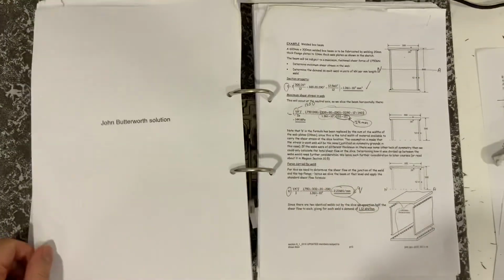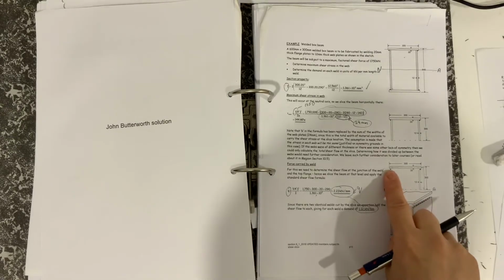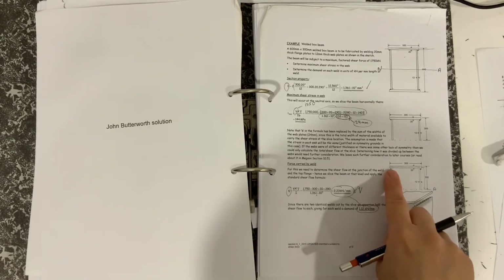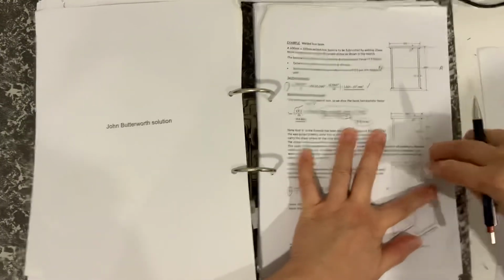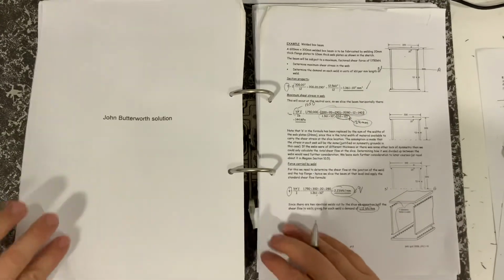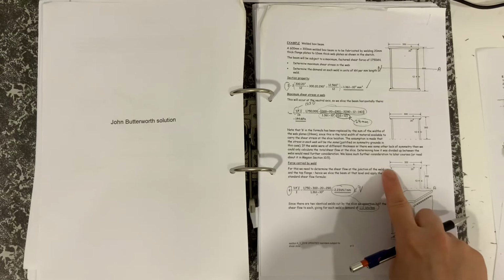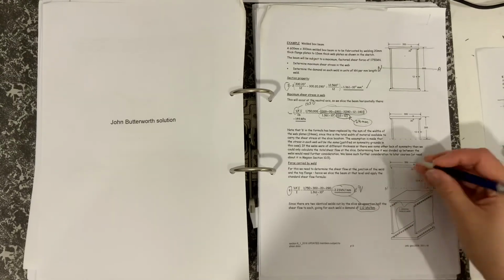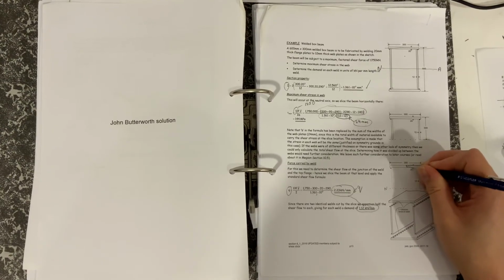So if you're not quite okay with that reasoning for why we divide the shear flow by 2, then another way to handle it would be, instead of taking the top slice from there, you could say, I'm just going to be handling that area there.